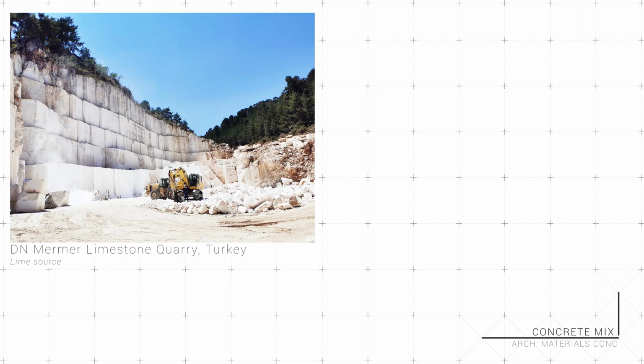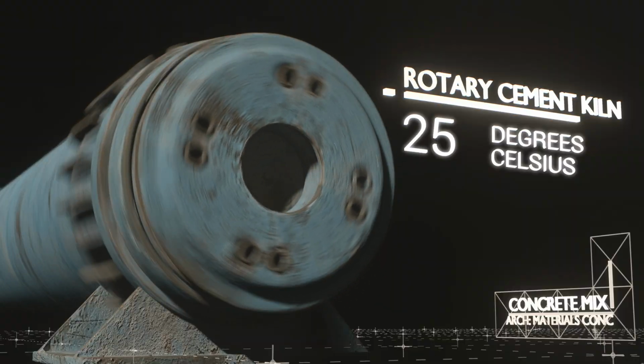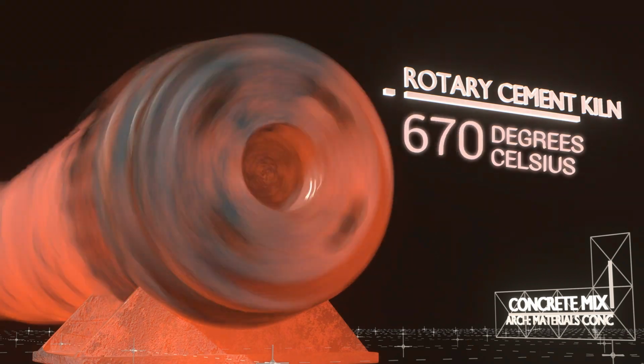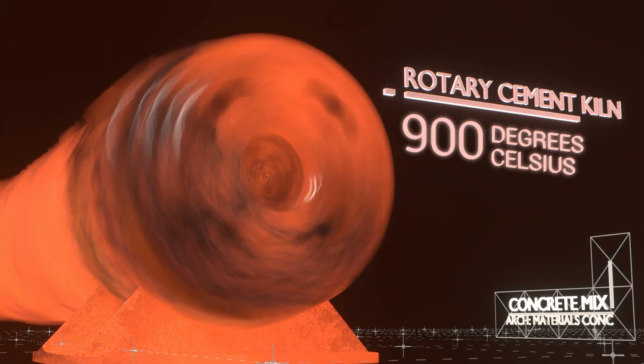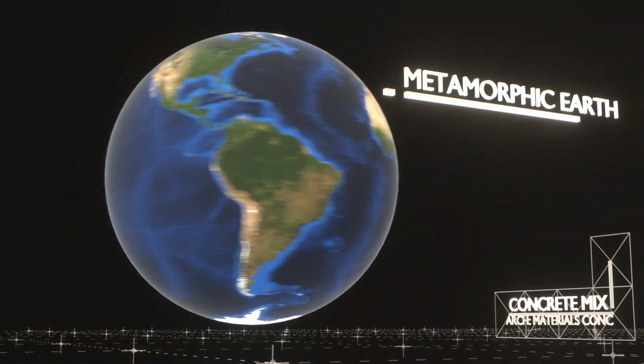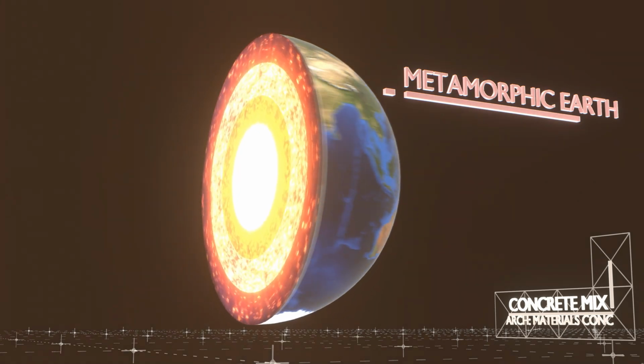Lime slated to become Portland cement is sourced from massive limestone quarries. At processing, the limestone is crushed, then dumped alongside shale and clay into massive spinning 900 degrees Celsius ovens. Inside, while rotating, the mix sinters, where immense pressure from heat compacts the rocks together into a single material, analogous to the Earth's deep underground churn, an unimaginable pressure cooker that compacts and bakes metamorphic rock.